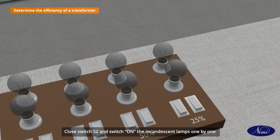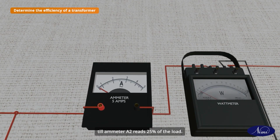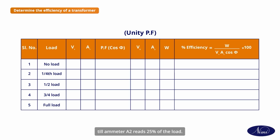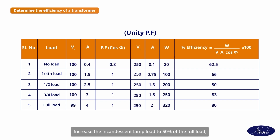Close switch S2 and switch on the incandescent lamps one by one till ammeter A2 reads 25% of the load. Increase the incandescent lamp load to 50% of the full load, 75% of the full load and 100% of the full load, and record the readings in each case.